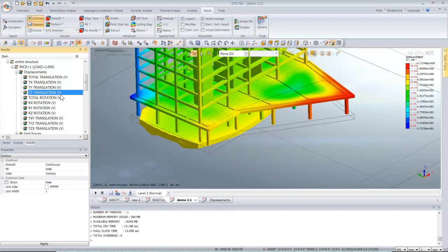So as compared to only the dead loads, we are going to look at the results. Let's firstly look at the probe results of our displacement in the Z direction. So we have the TZ translation, and we can simply click on the nodes. So this is minus 6.3791, as a displacement of this column, and then we'll go ahead to Gen.